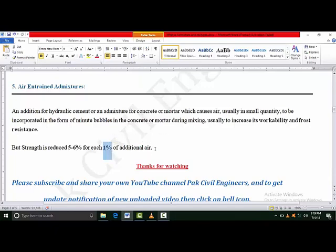If you use more admixture, meaning if the air content becomes 2%, then what happens is your strength will reduce by up to 10%. If your air content reaches up to 4%, then your strength will reduce by up to 40%.